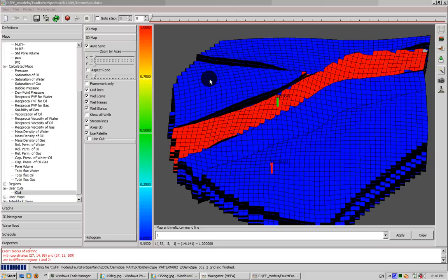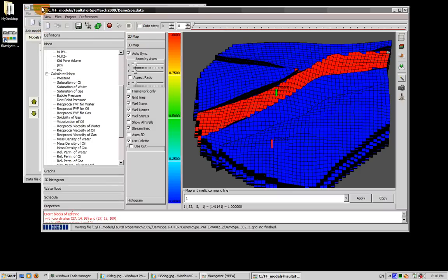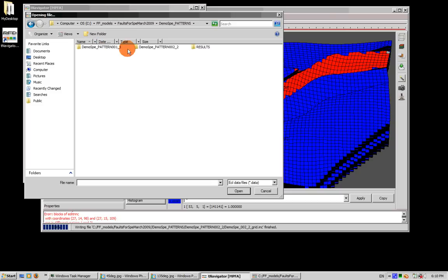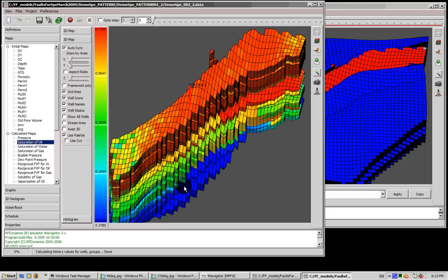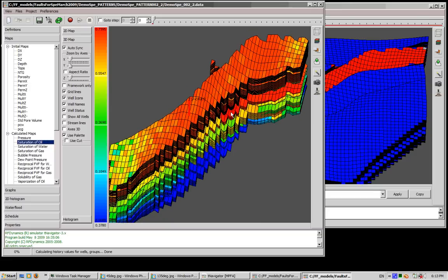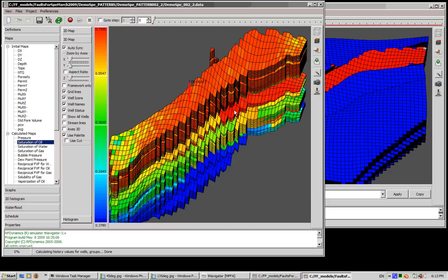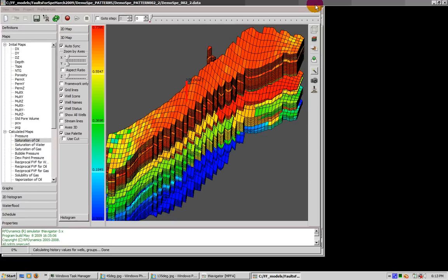The splitting procedure is fully automatic, and it goes around the blocks, wells, regions of PVT, SCAL, and so on, and divides them between the newly created fragments of the model. The split is finished. Let's load the newly created fragment. Okay. The newly created model is self-sufficient, also in Eclipse format, and identical in shape to the region we specified in the large model. Okay, let's do some work with the newly created fragment.